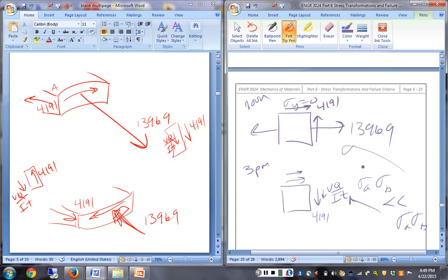If you have a very short beam, if you have a simply supported beam instead of a cantilever, it depends on your case. You should calculate the principal stresses for noon, 3, 6, and 9 just to say, oh, okay, it is 3 o'clock that's worse. And then you do your factor of safety analysis on the one where the principal stresses are the largest. In our case, our sigma A and B are going to end up being equal for noon or 6.